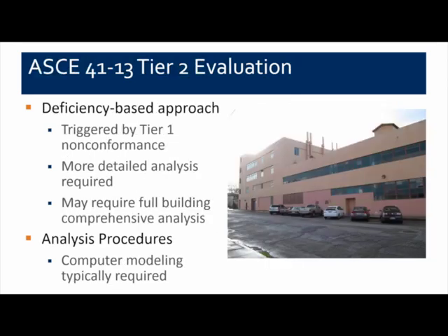Now the ASCE 41 also has a Tier 2, which is a more detailed evaluation methodology, and this is what's called a deficiency-based approach, in which case any deficiency potentially identified in the Tier 1 evaluation would require some more detailed analysis. This detailed analysis may require a full building evaluation, or it may be a localized evaluation of a specific part of the building. In many cases, the analysis is going to require some computer modeling of the building in order to do that evaluation.